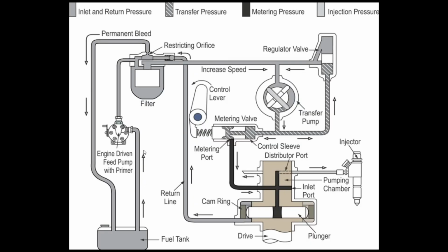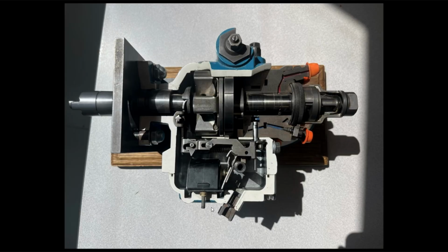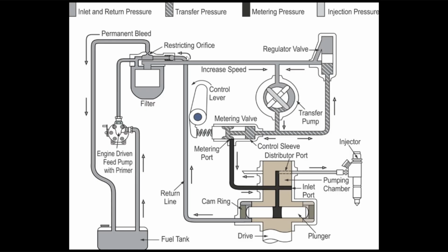This then pushes the fuel towards a secondary filter at a working pressure of about 3 to 5 pounds per square inch. Once the fuel arrives at this filter, particles larger than 5 microns will be kept out of the rest of the system. The reason being, the injection pump consists of very close tolerances, about 1 to 3 microns. Abrasive materials such as dirt or water will wear out the pump, causing a reduction in output or even complete failure of the assembly.